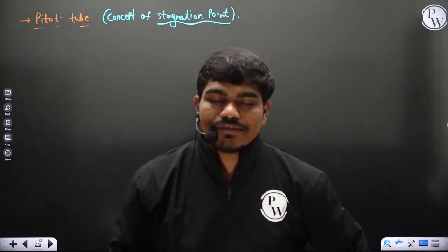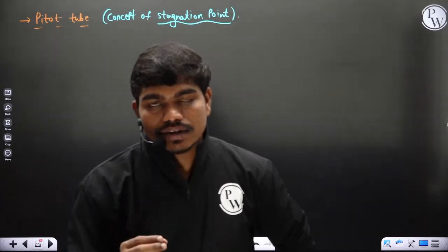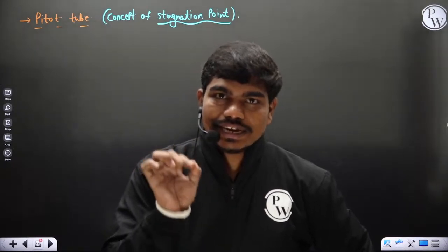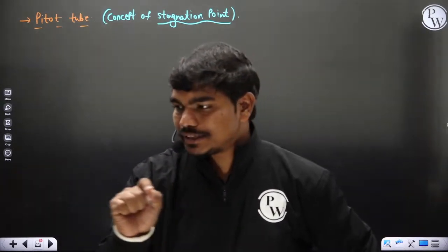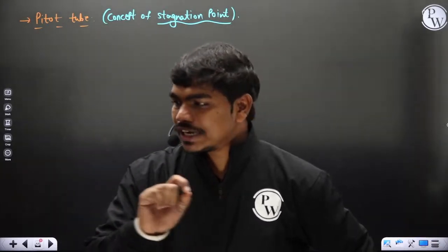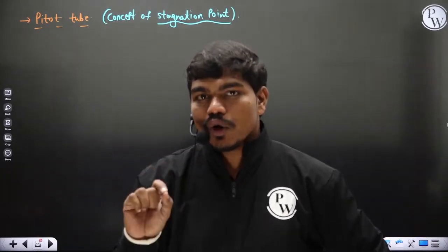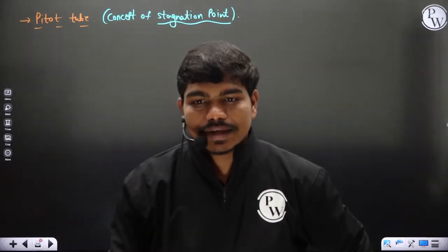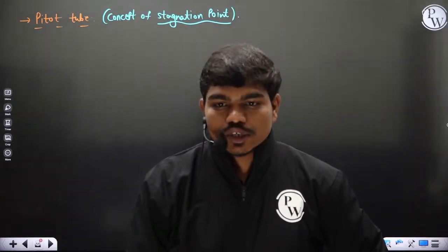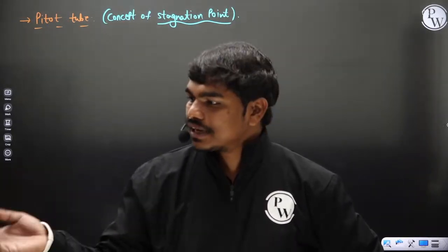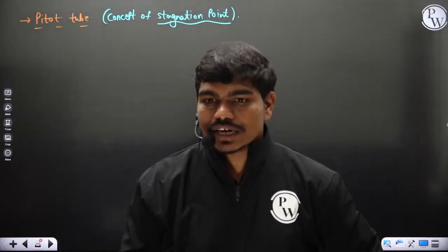So when designing any device, the main thing we should take care of is, whenever there is any process involving a pressure drop, you should check the pressure, normally when doing simulation or design, and make sure nowhere is the pressure low enough to touch the saturation pressure. Okay, so you mean when pressure goes below atmospheric pressure? Yeah, normally at atmospheric pressure, liquid water remains as liquid.